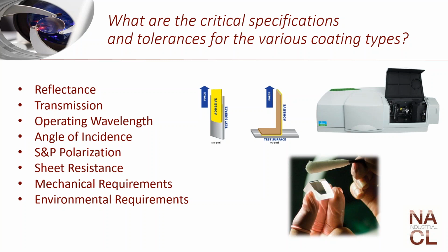Also, with visual defects, if you see anything that you don't like, a striation or anything in the coating, you can then apply tape and try to pull the coating away with a tape test. The other way you can measure abrasion is a delta over haze. You'd work the surface with your abrader, be it cheesecloth or rubber pumice eraser, and then you'd measure the light transmission. Your coated optic would be the zero, and then however much change there is to the light transmission after abrasion, you would set a passable record there. So those are some mechanical requirements.